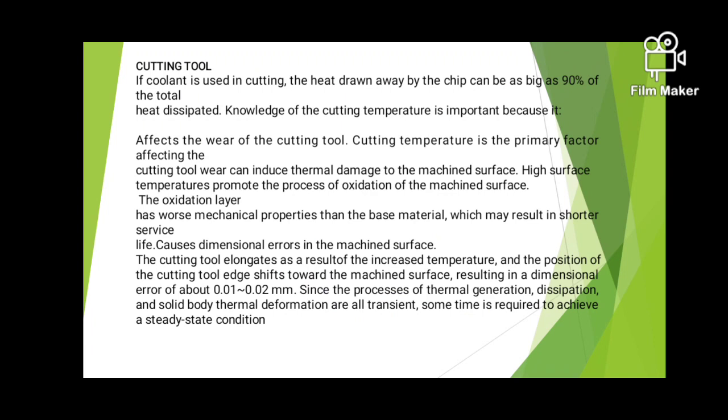If coolant is used in cutting, the heat drawn away by the chip can be as big as 90% of the total heat dissipated. Knowledge of the cutting temperature is important because it affects the wear of the cutting tool. Cutting temperature is the primary factor affecting the cutting tool.